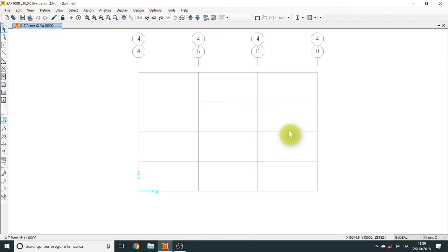I know that the steel material is more or less equal in compression and in tension. But we have a problem of slenderness and we have a problem of buckling. Eurocode 8, the seismic code of the Eurocode, says if you have this slenderness and you are not able to use a program that considers only tension, in the bracing you have to model only tension elements.